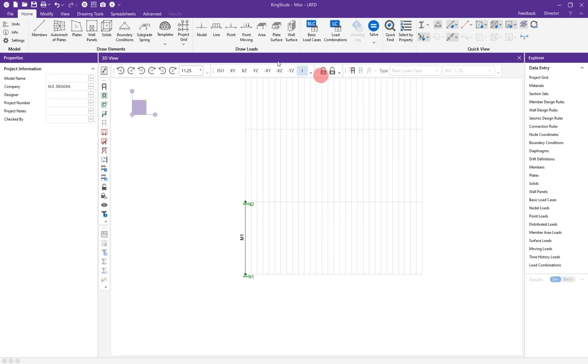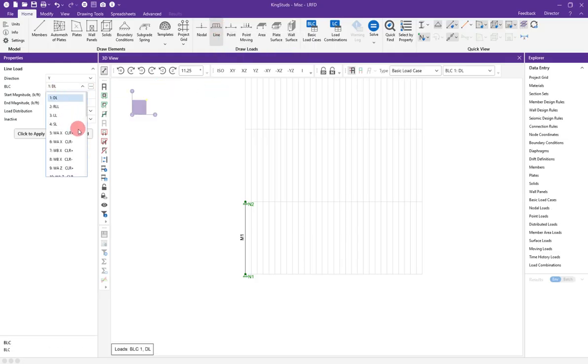All right, so when you go to apply a load, in this case I'm going to do a running load, and I want to label it. It doesn't matter which of these, but for the sake of this, we'll say in the y direction. I mean in the z direction. I was about to say, why is that the only one that doesn't work? So we'll just do z, and we'll go boom, full length and magnitude, and then we'll go 0.195. Click apply, and boom.